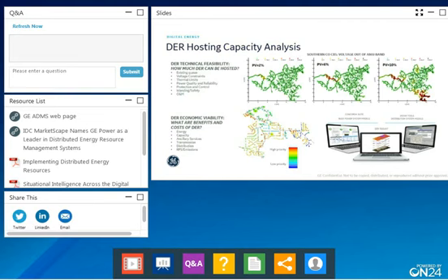That takes simulating DER trends of various types and running all types of network studies so that you can see where the constraints will come, and ultimately also being able to take into account the DER control modes that you will have to say, okay, maybe DERs are not just a threat, as Dave was saying, but also an opportunity to actually remove some traditional copper investment.